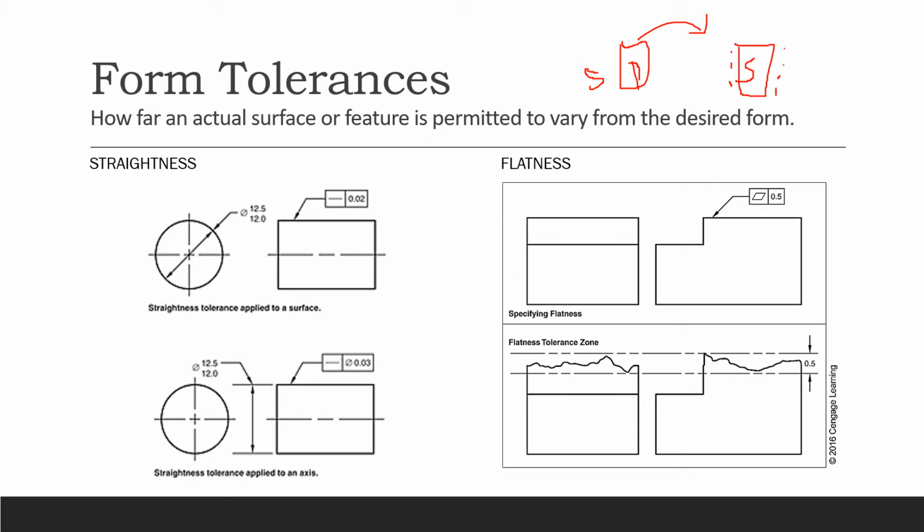And we're checking the straightness of the surface. It's got to be straight. You can come up a little bit. So if you see the surface, it's got to be like that. However, your tolerance zone can go this little, 0.02 up, like that, or down like this. Yes, and the same thing.